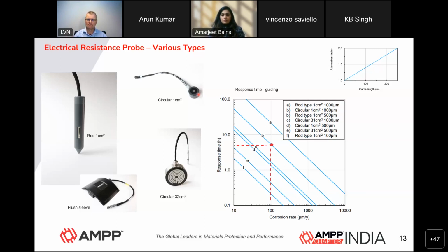We are seeing a lot of failures due to AC fault currents. And these are failures that actually affect the pipeline integrity? Yes. Because the fault currents could be almost 8,000-10,000 amperes, and if the pipe is very close, we have seen that the current enters the pipe and has caused pipe integrity problems. Usually the fault has a duration of only about 200 milliseconds, but that's sufficient to cause the damage, not only to the coating over the pipe. I'll share some photographs with you.